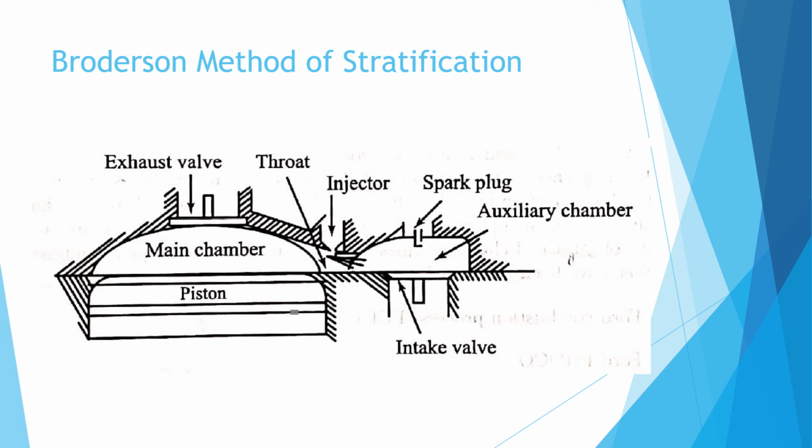For rapid and complete burning of this lean mixture, the main chamber must be designed to ensure proper turbulence. This will enable mixing of the hot burning mixture coming out of the chamber with the mixture in the main chamber.